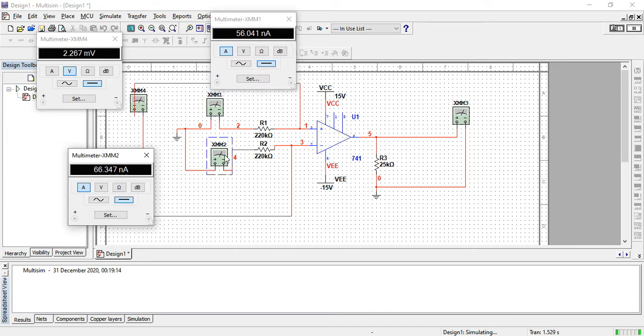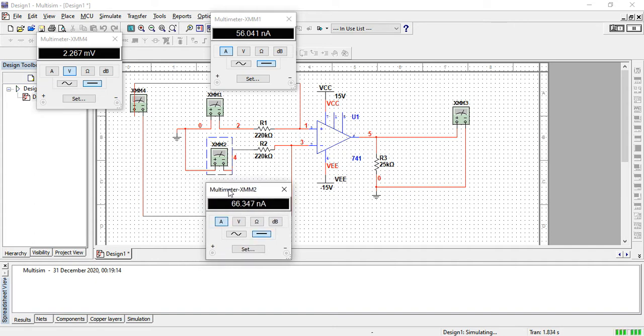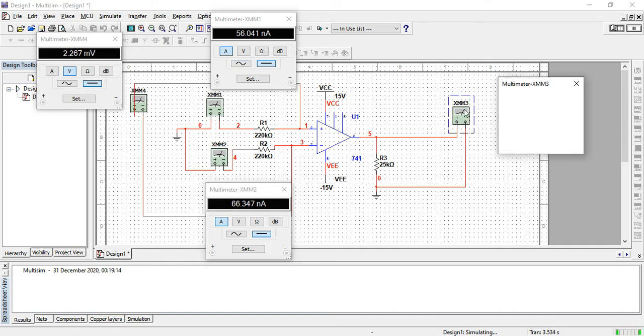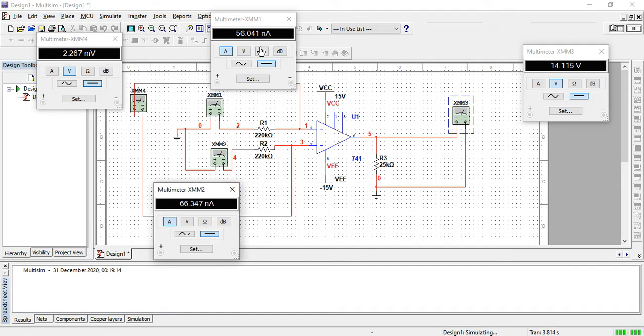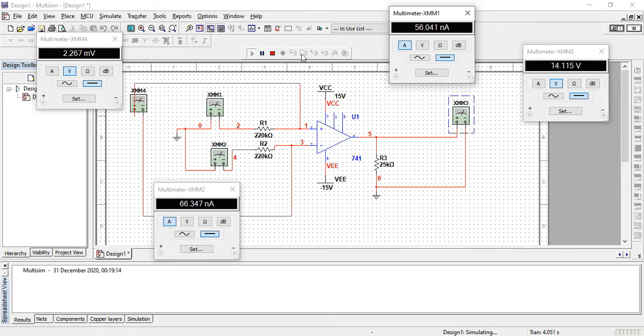There's a concept, if you want to search for it, mostly when they have a voltage, what they do is, for example, this is your offset voltage, you have grounded it, okay, both your terminals are grounded, this is your offset current, okay, and still you are getting amplification. So in actual scenarios, when you want to normalize this offset voltage, you add a potentiometer here, right, between the 1 and 5 terminals, and in that scenario you have to give your feedback, right, from your output terminal to your negative, right, as I said to you previously that feedback is negative.